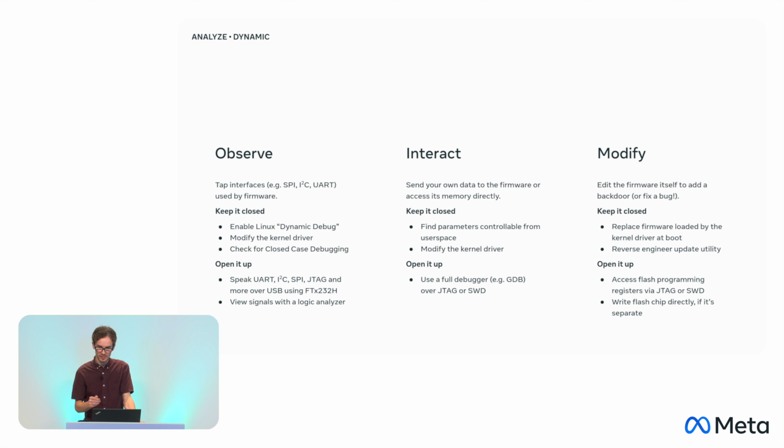And always when you're talking about modifying firmware, you have to be aware of any security measures that are there to prevent modification. Usually this is signing. So for example, bootloader firmware, pre-boot code on any modern phone will all be signed because it's establishing a chain of trust. So it starts at the very beginning with a public key that's burned into the chip itself, and it will only run code signed with that public key. And then that code will only run code signed with some other public key that it embeds. And eventually we get all the way up to the main operating system, each stage verifying the next stage.